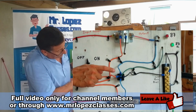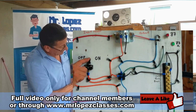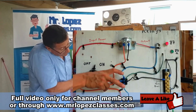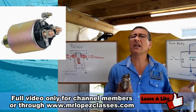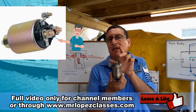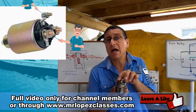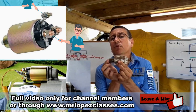Okay, in the external, right now I don't have power in the coil. The connection is off. When I power the coil, immediately the connection in between 30 and 87 is on and the light is on. The solenoid is basically a relay, but in the moment that the connection between A and B is closed, because the signal enters here, when the gap in between A and B closed, additionally an external movement is produced.